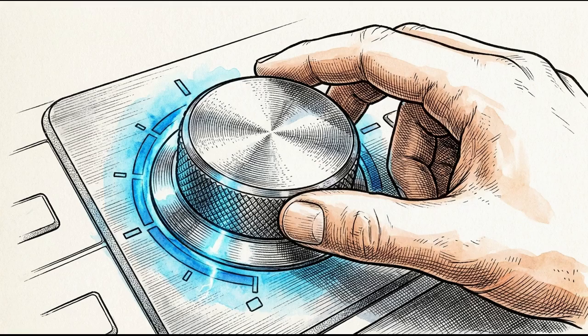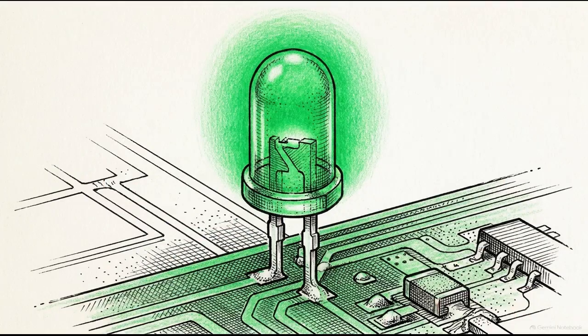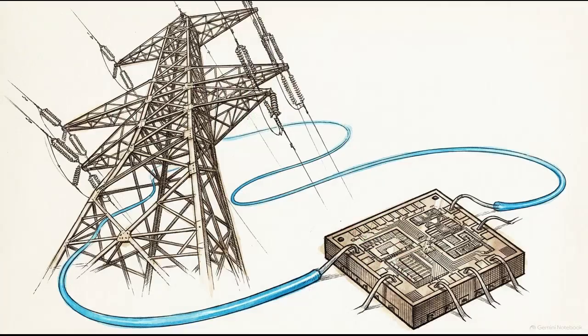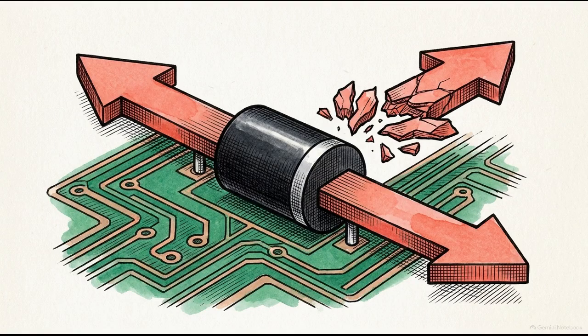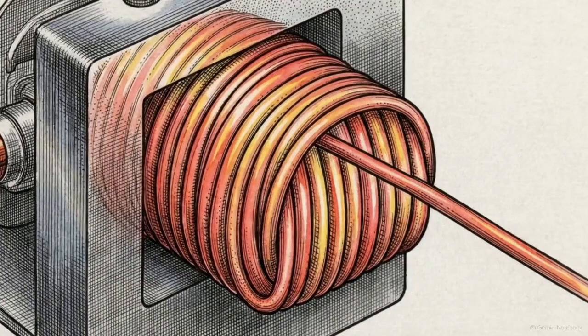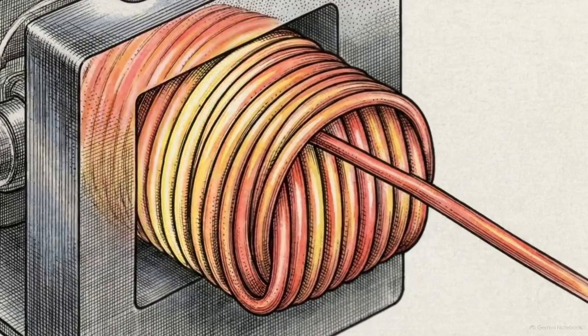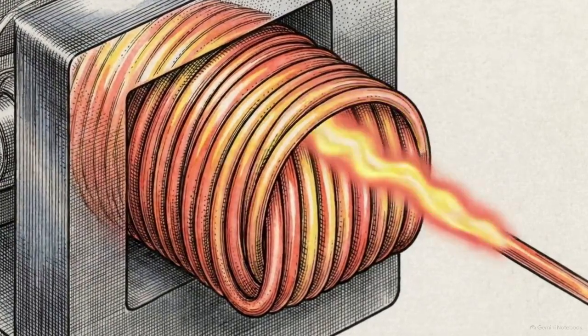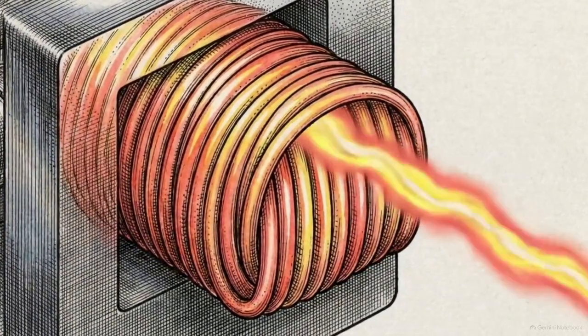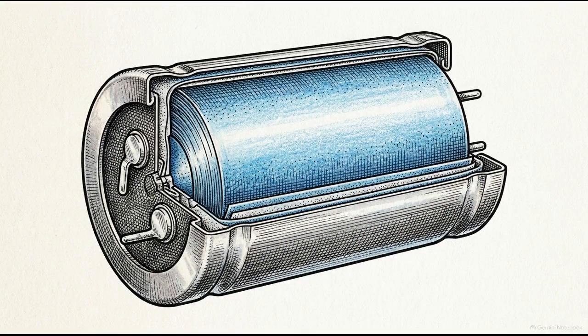Manipulating this time domain behavior is the final step. The capacitor ensures that the pulsing wave is smoothed into a steady flow of power. The conversion from grid power to device power requires overcoming a series of hurdles. First, a single diode enforces unidirectional flow but discards half the energy. Second, upgrading the transformer to a center tap topology inverts the negative cycle, doubling the frequency and recovering the lost power. Finally, adding a high-capacity filter manipulates the time domain, discharging stored energy to fill the voltage gaps.